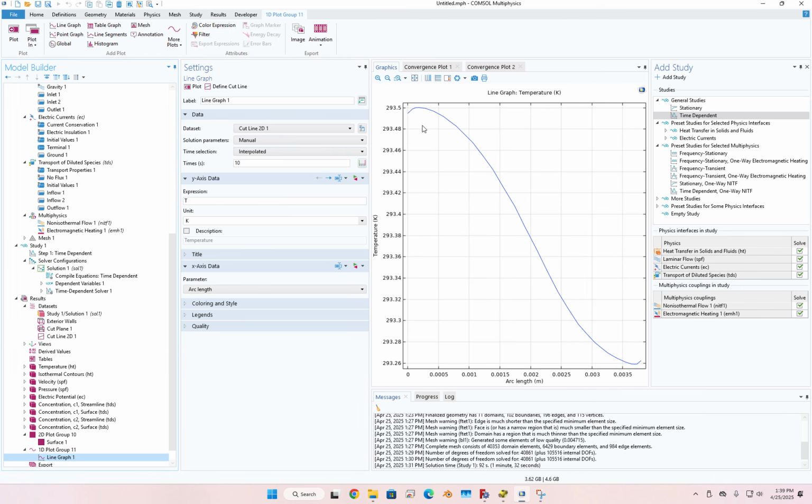So we can see that right where the fluids mix, the temperature of that channel is quite a bit higher, and right by the exit, the temperature of that channel is quite a bit lower. That's useful data. Super, super useful, because we can adjust our channel geometry to flatten that out a little bit more if we want to, which is fantastic.